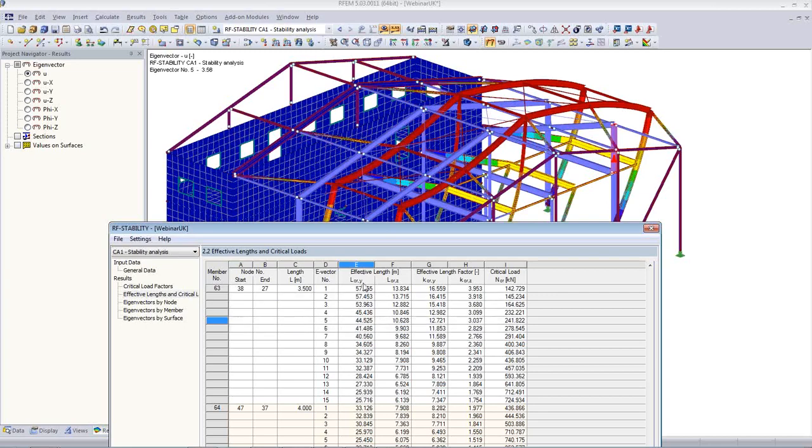And then we see here we have a buckling length of about 44.5, and I entered 45. So it's quite good. I have done this calculation for myself before, so I have a good idea about the buckling lengths, but this is how it would work.